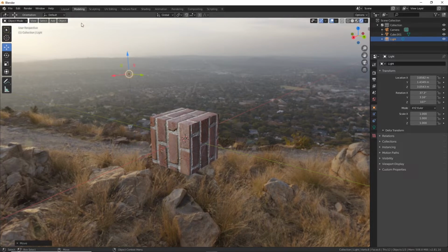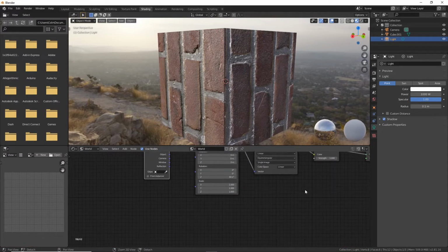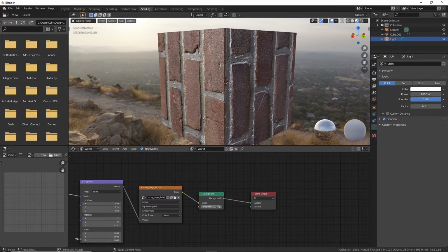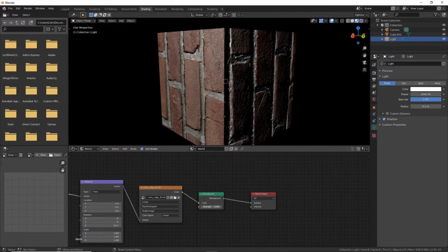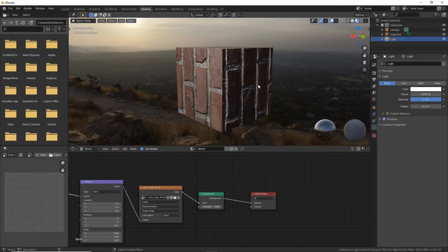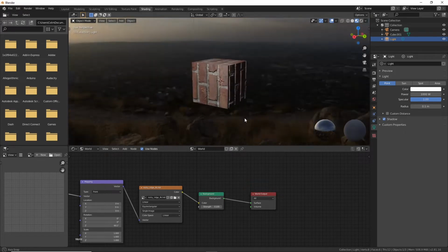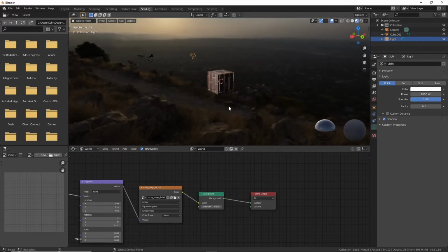To do that, you could go to shading, go back to world, and under the strength for the background, just take that down to like a 2 so that it's less lit by the background, or even a 1. So you still get some of this background environment shading, but now this light contributes a lot more to the lighting of the object.